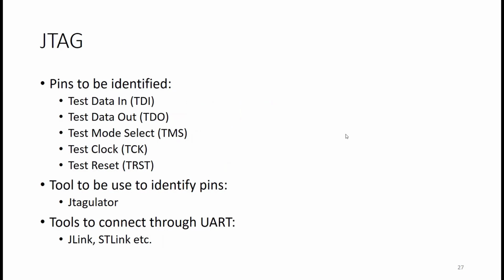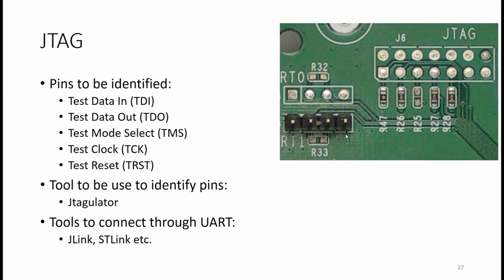As a common pinout, you need the five most common pins in JTAG, that is TDI, TDO, TMS, TCK, and TRST. Additionally, there would be a ground. As you can see in this particular figure, this is a 14 pin JTAG connector, out of which you need to identify all the pinouts required for the JTAG connection.